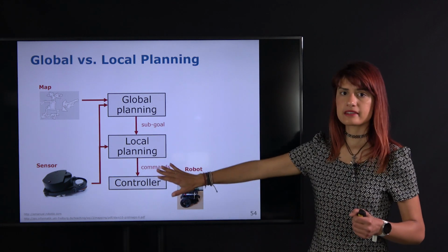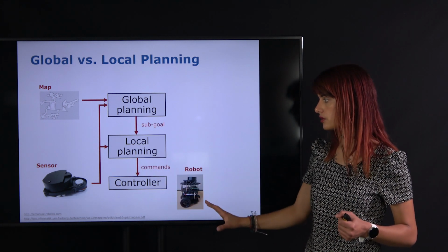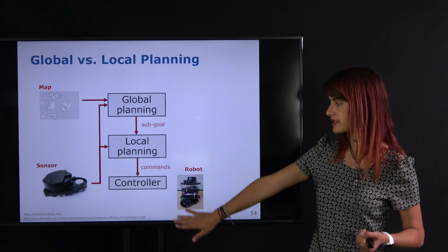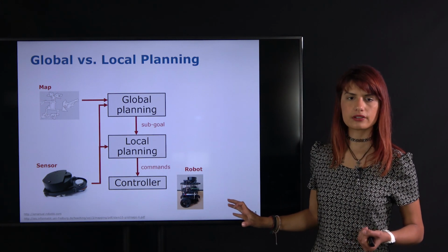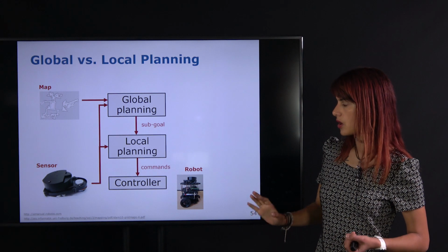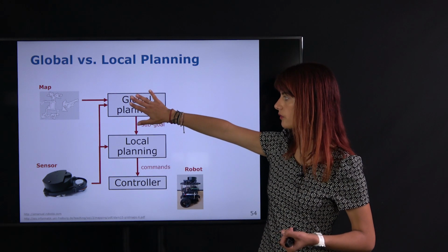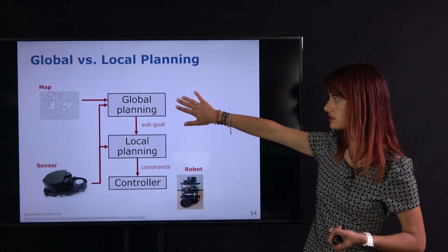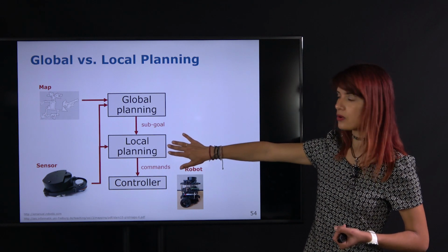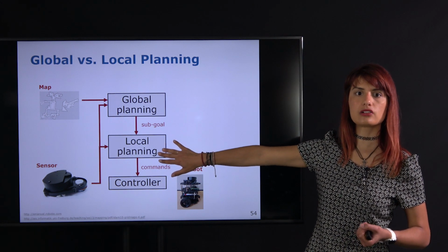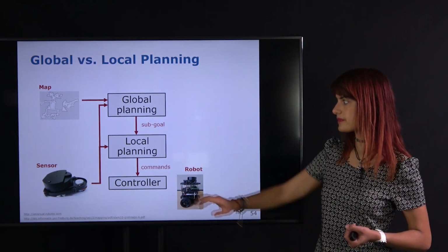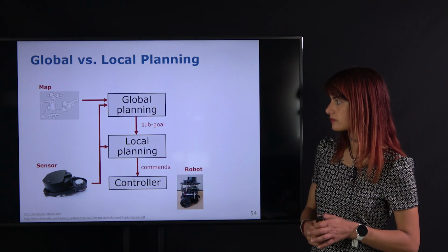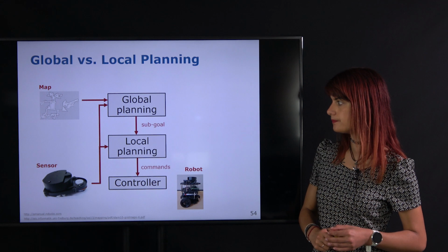The local planner then sends the commands to the robot controller, which is in charge of actually executing them on the real physical actuators and making this motion happen in the real world. Our sampling-based and search-based methods were over here in the global planner, and this is basically the task that we're considering with these methods. But we should also realize that there is typically a lower-level local planner operating that is in charge of performing these reactive and corrective tasks in our planning architecture.